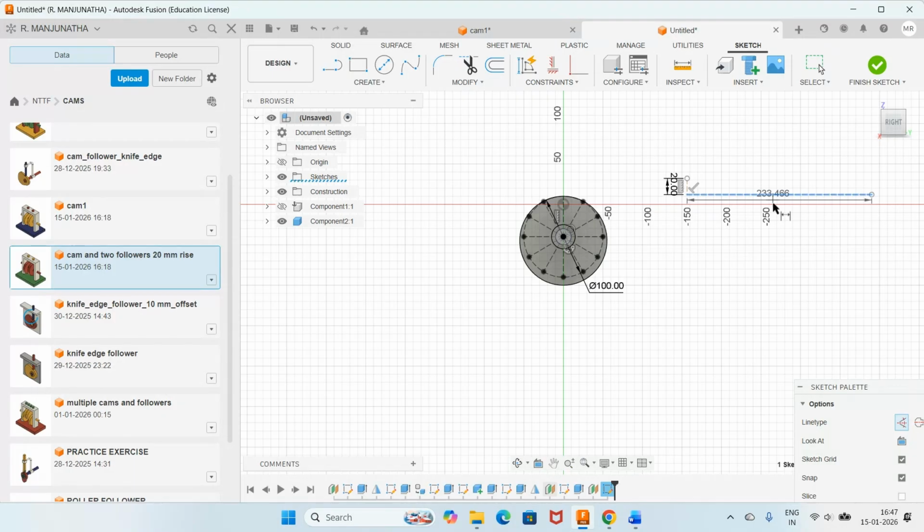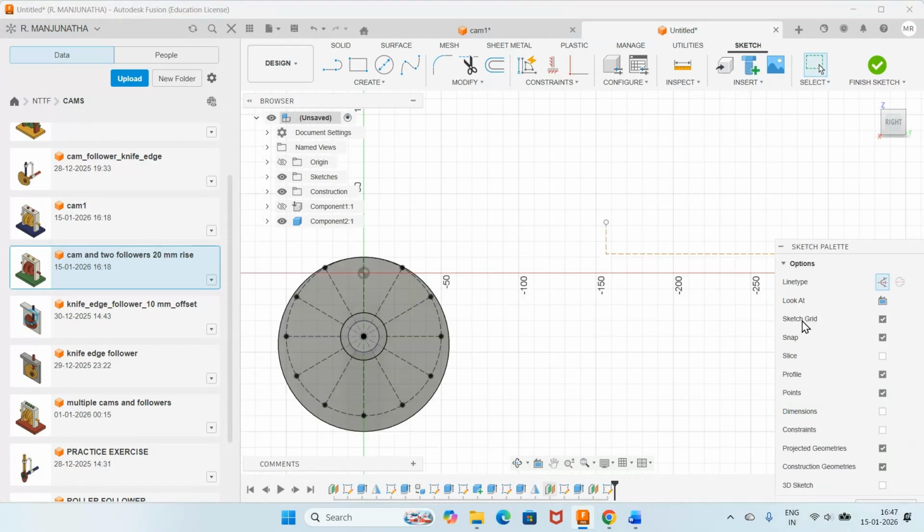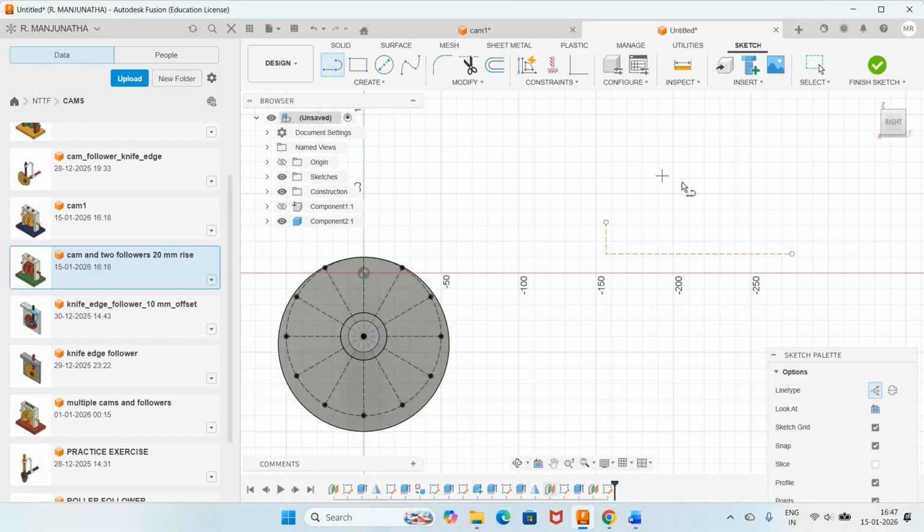Okay. Now I want to go for sketch, remove dimensions and also constraints. Then I will go for line, select this line and draw one vertical line. Similarly, I will consider any arbitrary point and then draw one more vertical line and go to constraint, say equal. The length of line should be equal to this. So you click on this and this line. Similarly, I will go for equal, select this line with reference to this line. So we go to dimension between these two. This dimension will become 60.